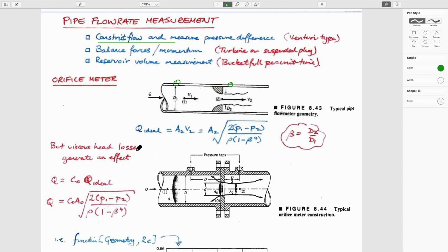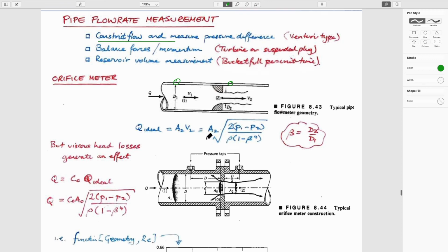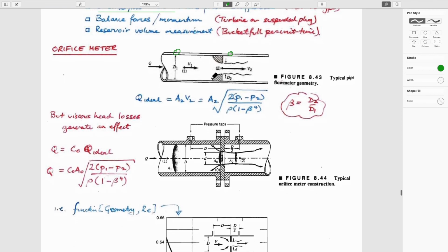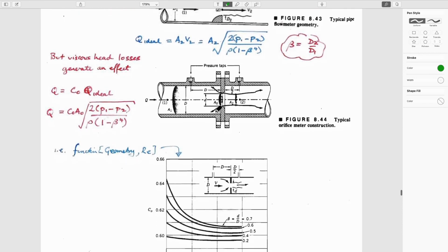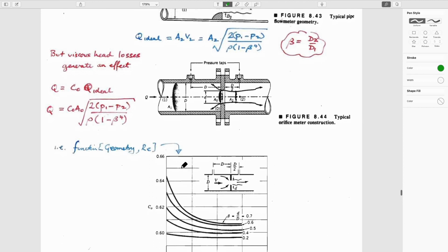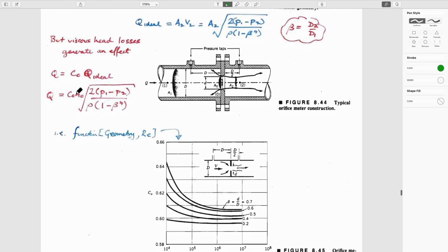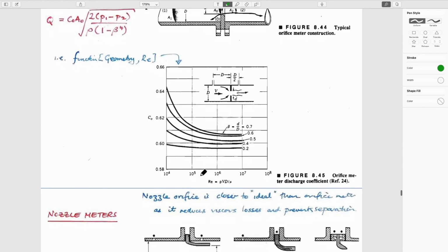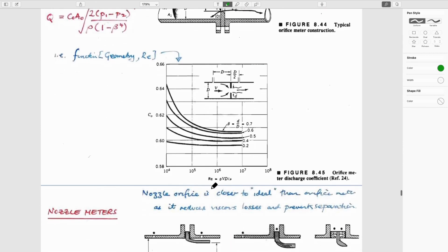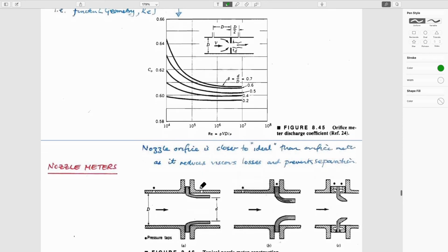And that's what's done. We talked about weirs, where you have a weir across a river and you measure the upstream and downstream levels. It's akin to doing this. And you can imagine this being an orifice meter, where you have an obstruction in a pipe and you measure the pressures. Depending on how sophisticated these orifices are, you can calculate correction factors, which you apply to get the correct flow rate. And you could imagine that these correction factors vary as a function of Reynolds number.